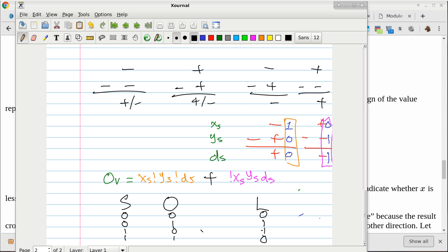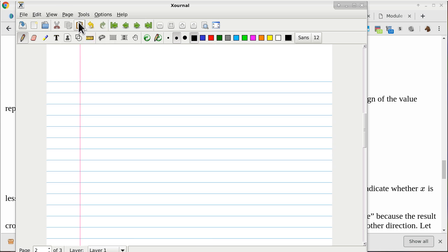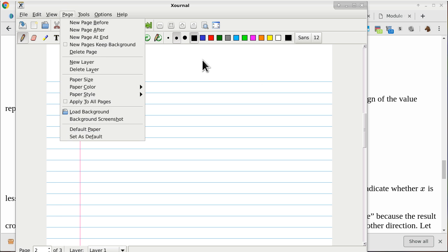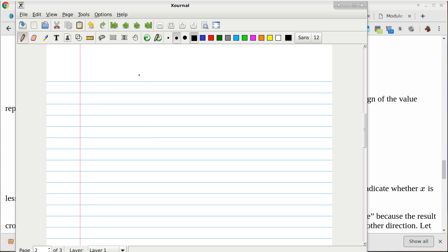So we look at this truth table. Every time we look at a truth table, the bottom line is, can we do this using logic gates? Have we seen something like this many times already? What gate do we use to do this? Exclusive OR. Very good. So what this is telling you is, once you have the sign flag and the overflow flag, you just need an exclusive OR gate to give you the L flag.